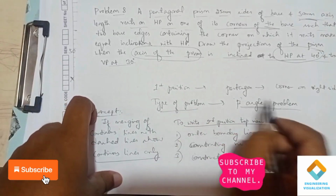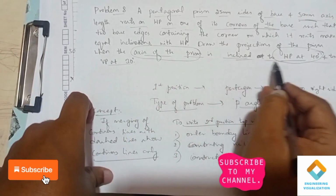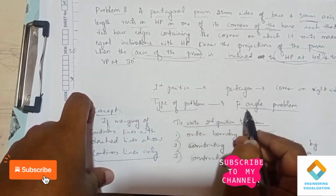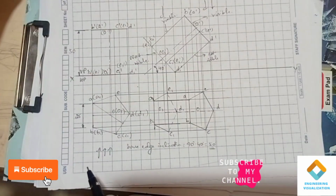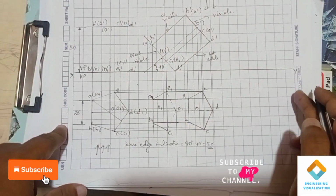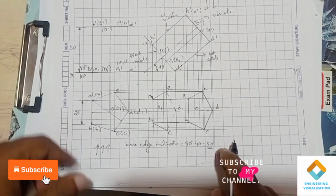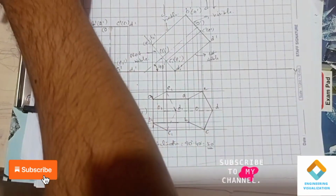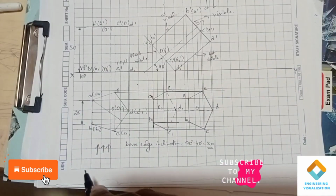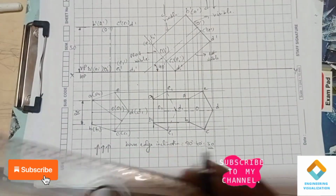Now the type of the problem here is beta angle, because they have given the axis of the prism is inclined to HP at 40 degree and to VP at 30 degree. So for that angle line we have to draw like this. From the reference point I will draw an angle line for 30 degree. The inclination to VP they have given in the question is 30 degree.